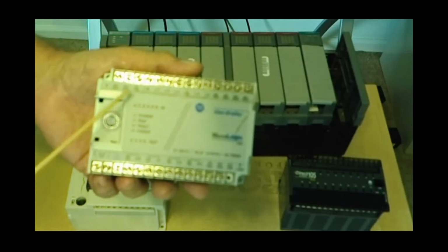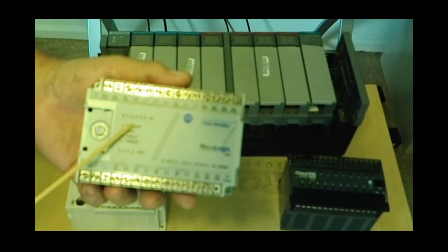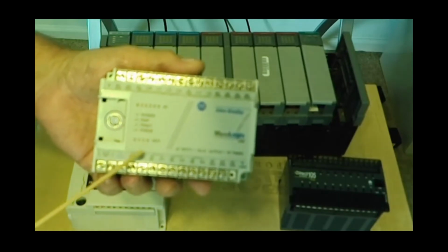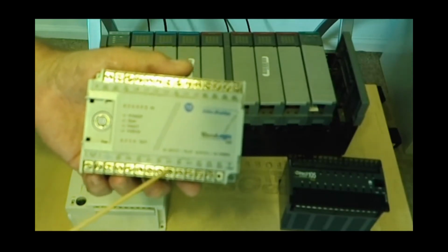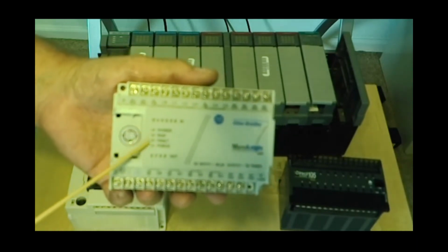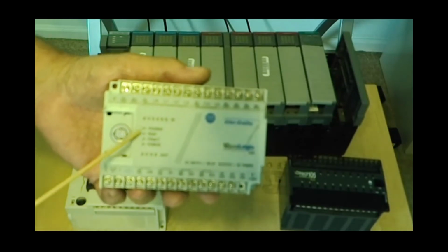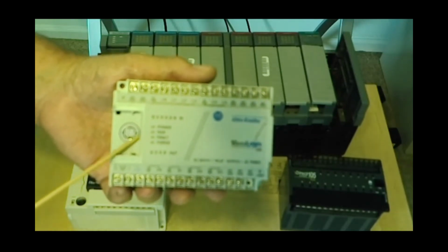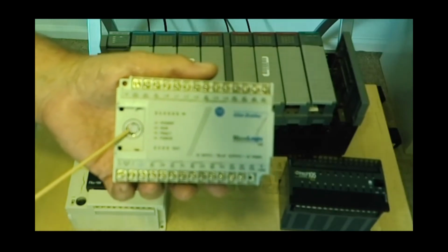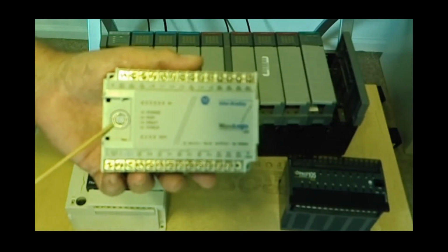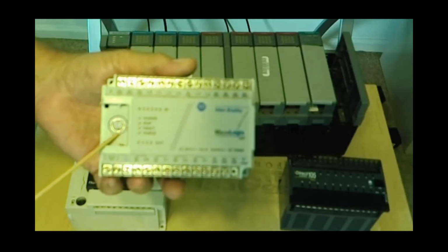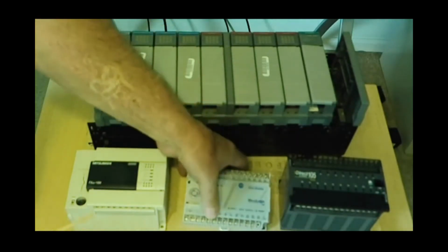The indicator lights identify the condition of the individual screw terminals. If this screw terminal is activated, that light will be on. Same thing with the output. If this screw terminal is activated, that light is going to be on. And again, you have basically right here the indicators for the processor: power, run, fault, and force. And every one of the CPUs is going to have what's right here, a programming port. This can range from all different types, from telephone jacks to USB to right here these RS-232 jacks. There's all kinds of these out there.